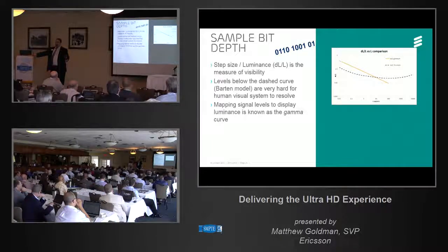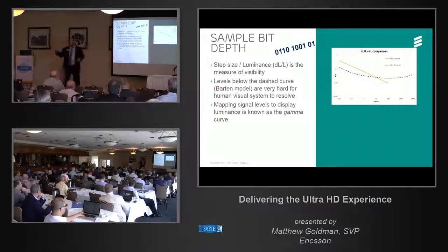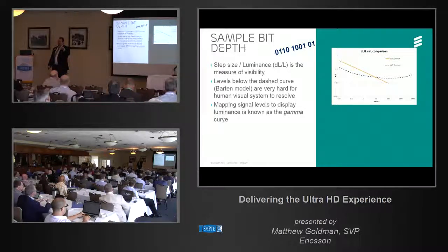Everybody who's had beginning engineering knows that with digital values, you're representing discrete values. You're quantizing, in other words, into steps. The more digital value depth you have, the more steps you have in a set space, and the tinier the steps. You only have 8 bits, so 2 to the 8, which is 256, is the maximum number of levels you can have. That's your step size. How does that translate into brightness? You have the same brightness until you get to the end of a step, then you use the next value and jump up a step.